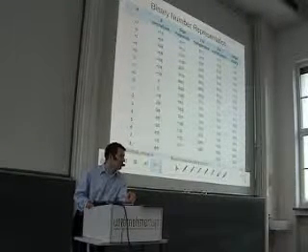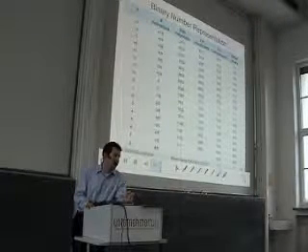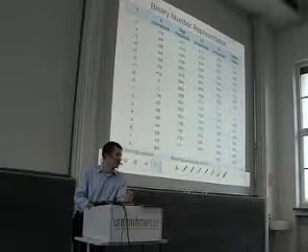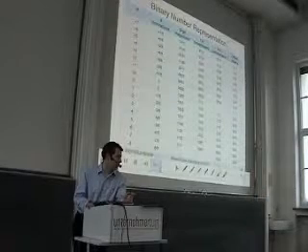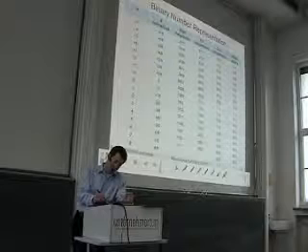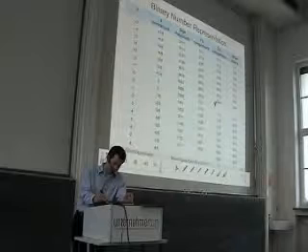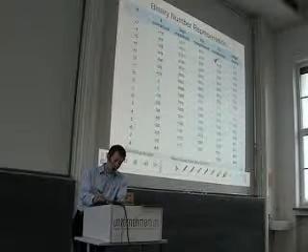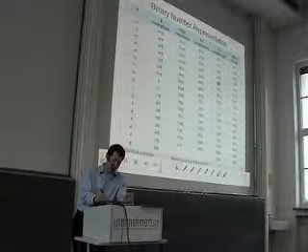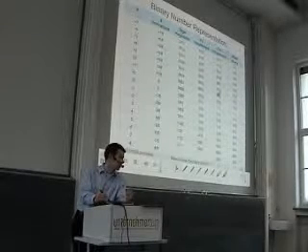And what you are used to use is usually the 2's complement representation of negative numbers. This is the number system that is most often used in all digital signal processing systems and processors. The 2's complement means that if we have positive numbers, then the most significant bit is always 0, and all the other bits correspond to a normal binary number system. So we count up from 0: 0 0 0 0, 0 0 0 1, 0 0 1 0, and so on and so on.